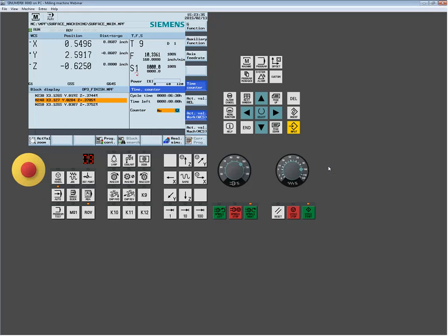A lot of times that will hurt your surface finish because you're restricting the cutter path too much and you get a lot of imperfections in your surface. So now we start to see, just from dropping from a half-thou tolerance to a 1/10 tolerance, I went from a 7-minute 48 cycle time to 11-minute 42. So what's that? 4 minutes increased. On a not even 8-minute cycle time, I took that cycle and almost added 50% to that cycle time. That's quite a bit, especially if this was a 2-hour cycle time.